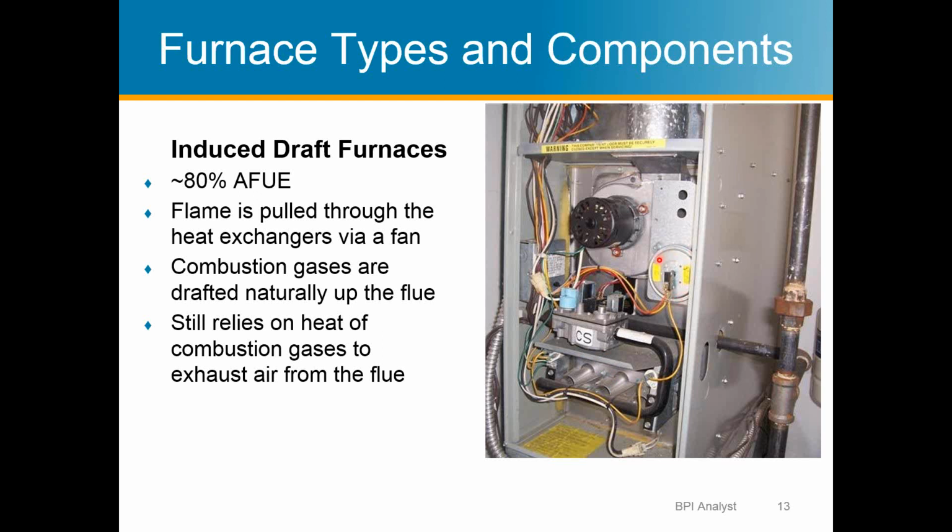This right here is a pressure device measuring pressure. I can't think of the term right now, but essentially what it's doing is making sure that the fan is running by measuring pressure. Because if there's not a negative pressure in this pipe, it'll signal to shut the system off. I think that's about all we got there.